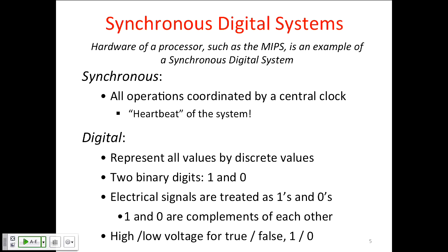Digital, what do we mean by a digital system? Well, a digital system is one that has quantized levels or digits representing the state, as opposed to an analog system. An analog system would be like some voltage value encoding a value. In a digital system, there are discrete steps, and those are the digits. In all the systems we work with today, there are only 2 digits, 1 and 0. So everything is binary, and zeros and ones are the 2 values any signal can have.